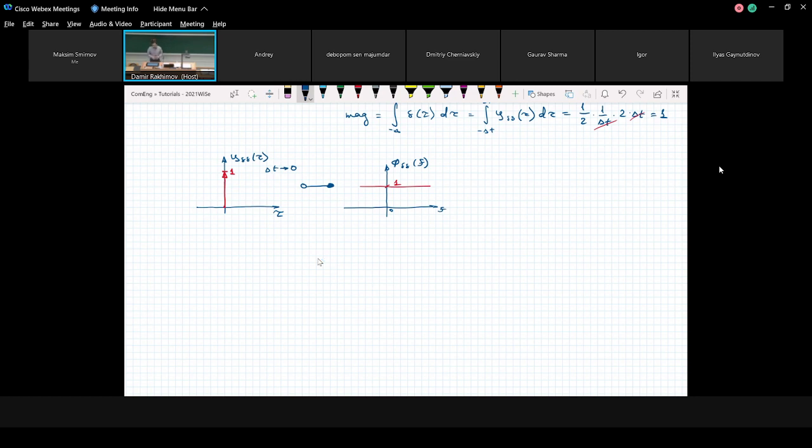And then we can easily describe our processes with this finite power. So for this reason, for finite signals, or so-called energy signals, we use the energy spectral density or energy correlation function, and for periodic signals or stochastic signals, the power spectral density. I don't remember if we have a letter for energy. Okay, it was a question, yes. Okay, other questions? Okay, if not, then we go to the next task.